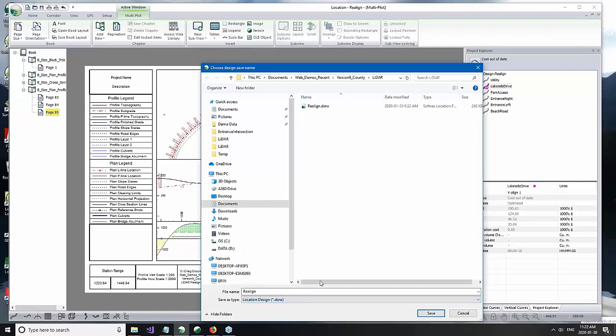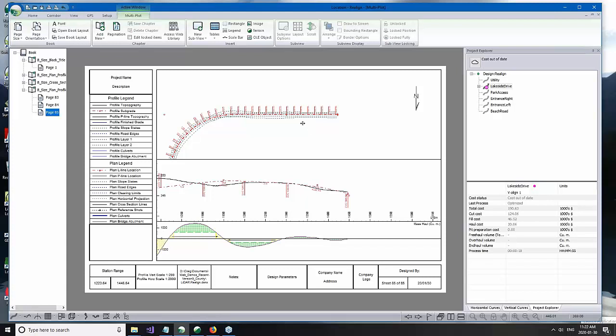Check out Enza on the web. If I had a handheld here, I'd get this chapter appearing in Enza with GPS functionality. The GPS is only going to work in the plan view, but I can track where I am in the plan view on my Enza. So if you're going out in the field and want to see where you are, it's quite a useful function.